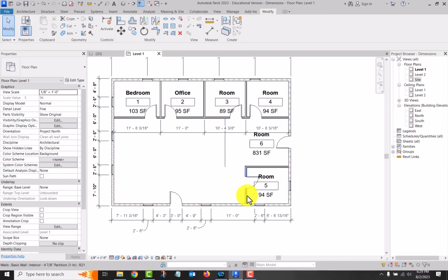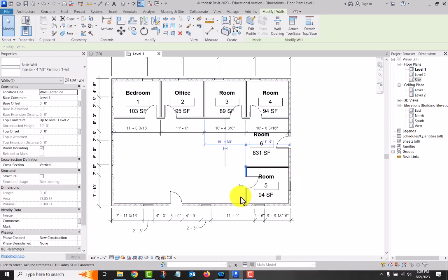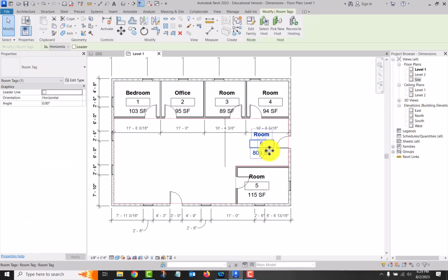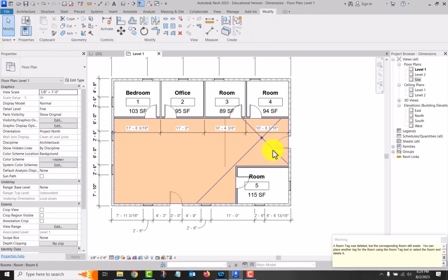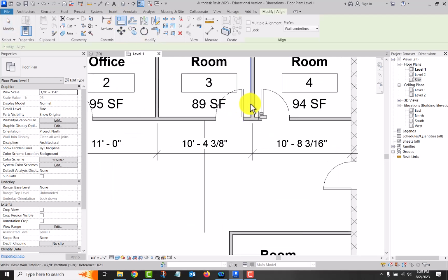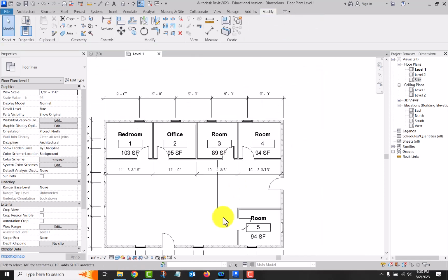But if we hadn't had that problem, okay. So I delete those rooms out. That'll clear us up. So let's go back and align again. And I choose those, and now it gives me the option to lock it. And so if I lock that constraint, now those walls are constrained together and they won't move.